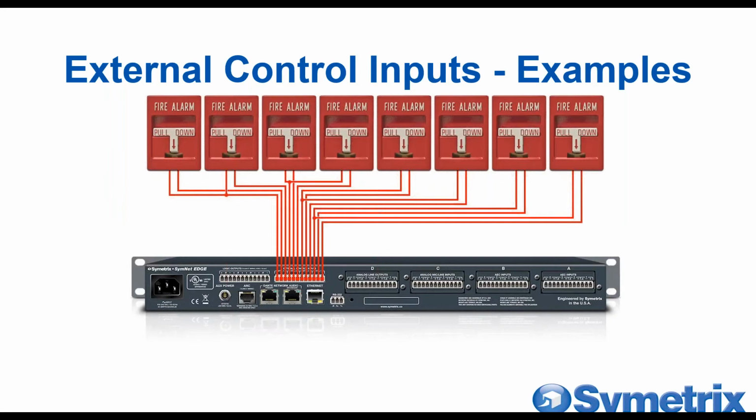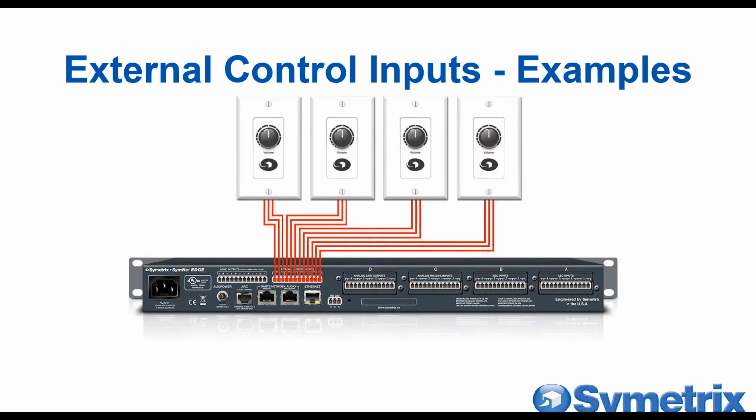Probably the most common example of using the general purpose inputs, or external control inputs as they're known in our universe, is triggering an emergency system mute based on fire alarm panel status. Another super common usage would be to use them as a volume control, where you have an RC3 or just a standard 10K pot wired in, and that would usually be driving an audio fader inside the DSP, or maybe driving a control fader that's got some scaling on it, that sort of thing. We'll look at that in Composer as well.